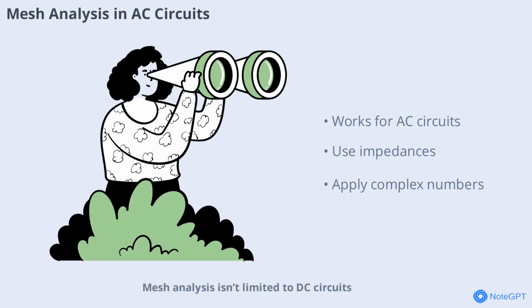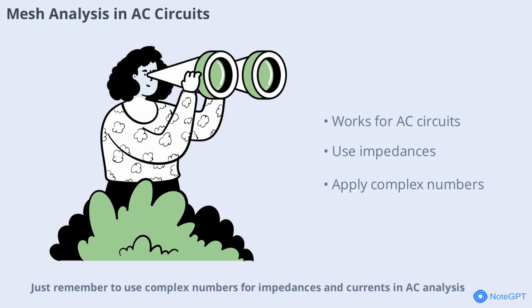Mesh analysis isn't limited to DC circuits. You can apply the same principles to AC circuits using impedances instead of resistances. The process is similar: assign mesh currents, write KVL equations, and solve for the unknowns. Just remember to use complex numbers for impedances and currents in AC analysis.